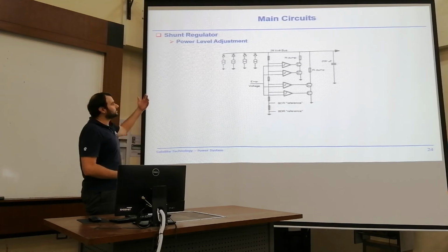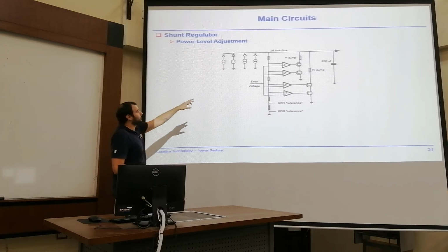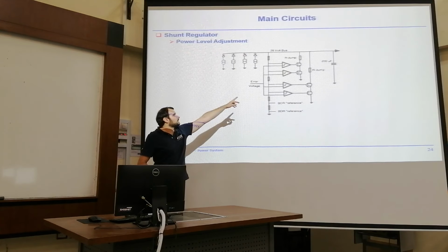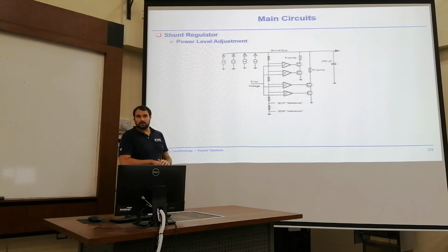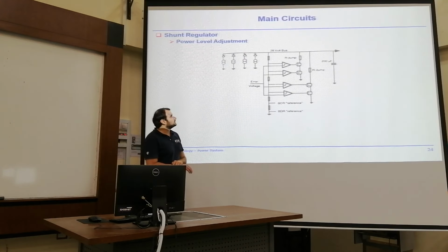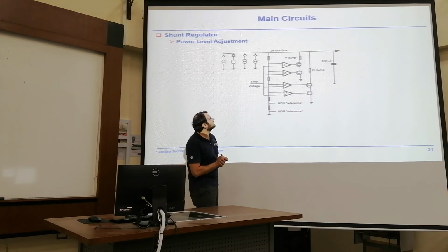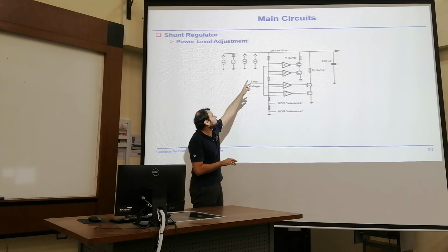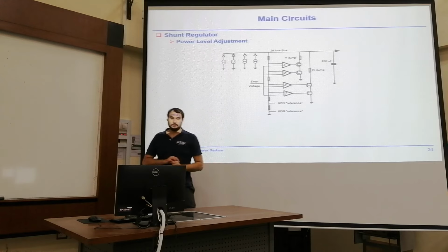And if you are above this reference voltage, your negative switches, your MOSFETs there, are closed, they don't come back, and so there's no connection from your voltage bus over the shunt to the ground.